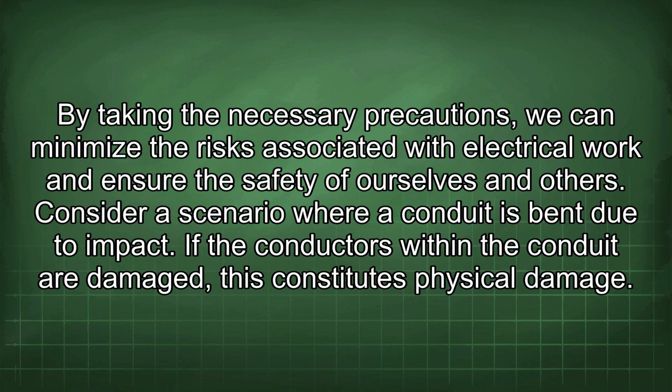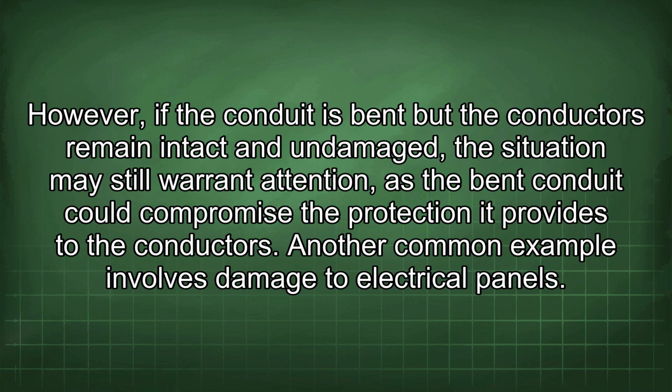Consider a scenario where a conduit is bent due to impact. If the conductors within the conduit are damaged, this constitutes physical damage. However, if the conduit is bent but the conductors remain intact and undamaged, the situation may still warrant attention, as the bent conduit could compromise the protection it provides to the conductors.